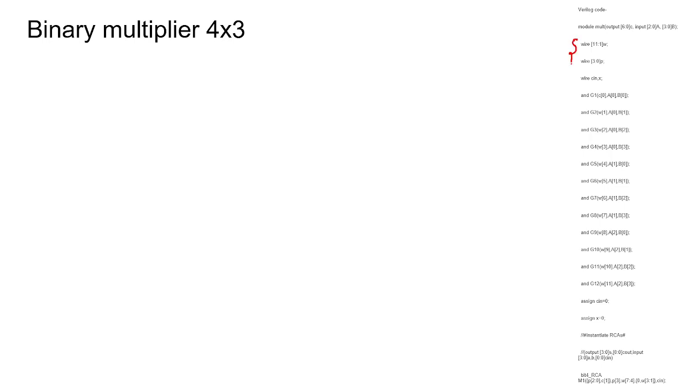So I have defined this W and P as wires, and instead of saying P1, P2, P3 separately, I am defining it as a register, so while calling, I will call P of 0, P of 1, P of 2, like that. And here itself I am defining the 7 outputs, 3 bit A and 4 bit B, and generating all the 11 W by applying the AND gate primitive cell, and then instantiating the ripple carry adder 2 times. Okay, this we will try.